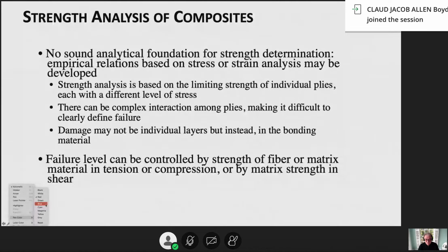A material fails because typically there's some structure in the material fiber, some crystal structure in the matrix, some voids, defects at the micro level that initiate something. And those cracks grow and then cause either the fiber or the matrix to fail.